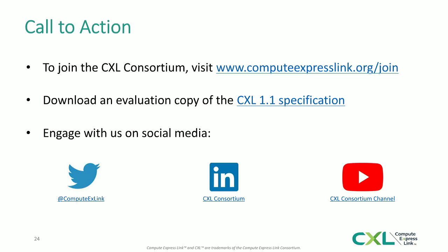What is the purpose of meta value? Is it for cache coherency? Sorry, Elsa, you broke up a bit there at the end. What was the question again? The question is, what is the purpose of meta value? Is it for cache coherency? Yes, that's correct. That's the typical usage. So you can share the state of the line that way. So, whether it's exclusive, shared, or any, for example, depending on what your coherency protocol is, that's the intent, to provide the state of that line.